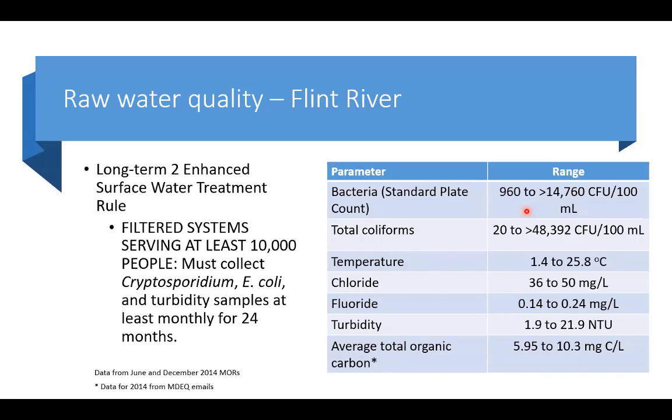It also has a significant impact on water quality in the distribution system. At higher temperatures, chlorine will decay much more rapidly, so you'll have more challenge at maintaining a chlorine residual throughout that disinfection system.